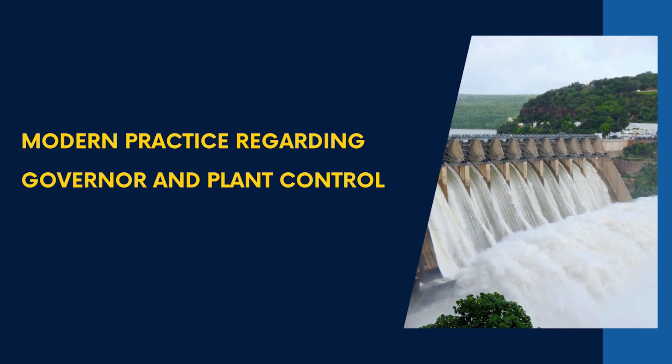The manpower available for small hydro plant operation is unskilled, and further adequate supervision is not feasible. Load factors for standalone micro hydels are usually low, affecting the economic viability. Flow control turbine governors are expensive and not recommended for small hydro units in the micro hydel range. Electronic load control governing systems with water cooled hot water tanks as ballast load, for unit sizes up to 100 kilowatt, can be used. So, these are the various mechanisms of governing a hydro turbine, or hydel power plant.